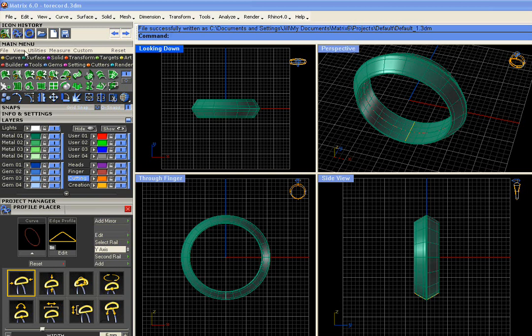in that color. We'll go to the curve menu, find the polyline tool, or the polygon tool, which is in the second row of buttons. The second light brings you to 2 more rows, so there's 6 rows total. And here's the polygon tool. It's going to ask for the center of the inscribed polygon. Number of sides is 5, which is correct.